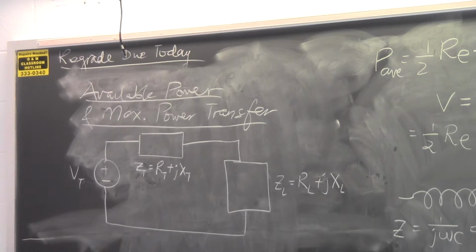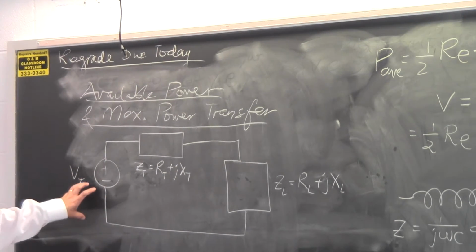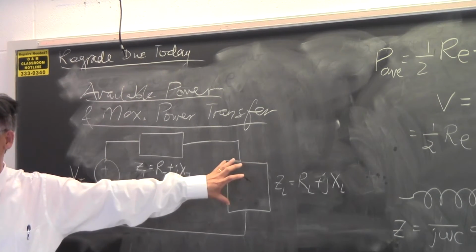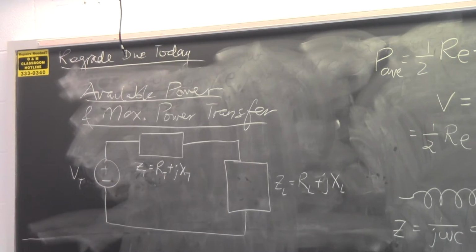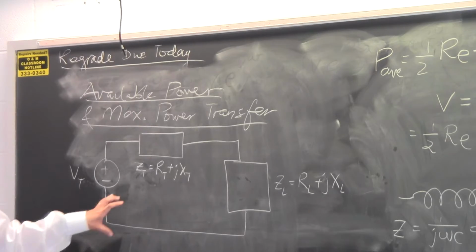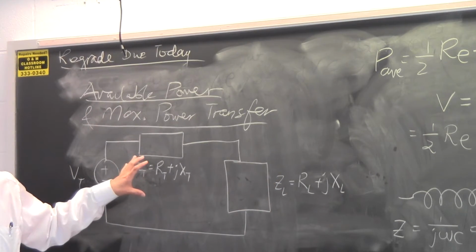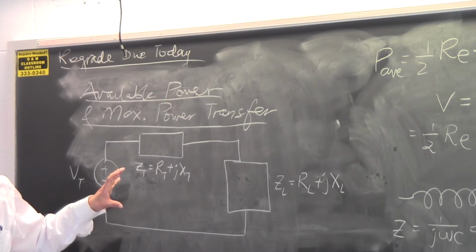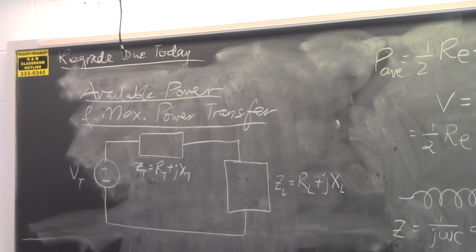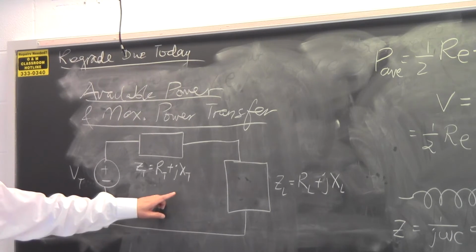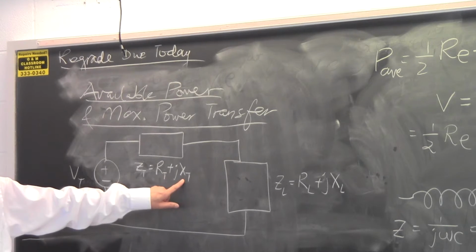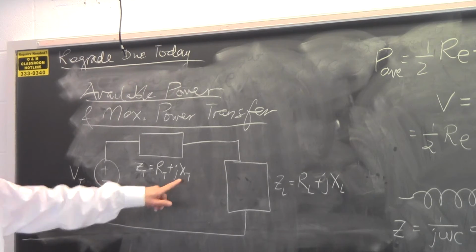So how do I adjust the load so that I have maximum power transfer from the source to the load? Set it equal to what? To the Thevenin. Not the same. Okay, that is where it departs from what you have learned in resistive network. In the resistive network, you set this to that, and it works there, but it doesn't work here. Okay, so this is one departure from what you have learned in resistive network. But just a nomenclature: this is called a reactance.